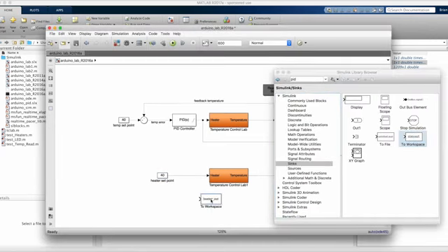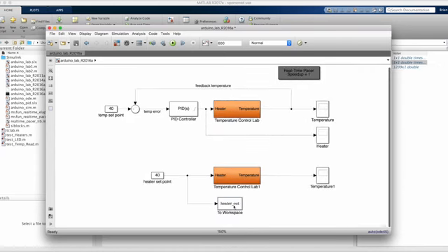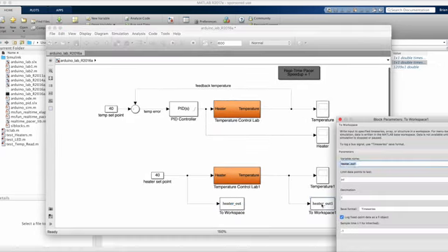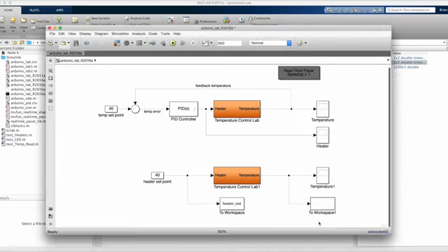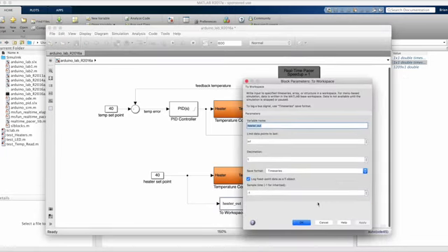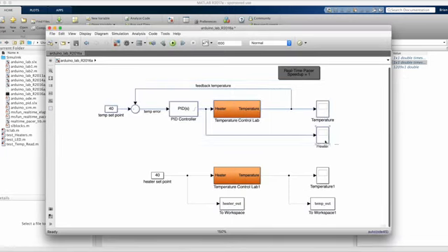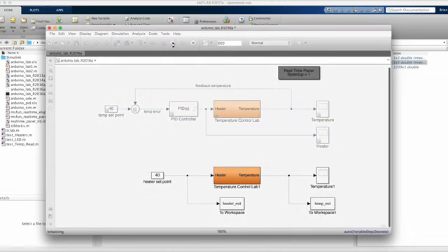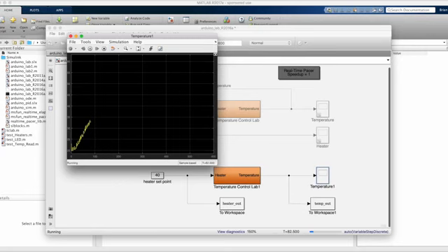For system identification, we could take the white box approach, taking note of the material properties and the dimensions and write out the differential equations directly. However, we have the hardware, so let's fit a transfer function to our real system. The way I'm going to do that is by applying a step function to our system and recording the step response. This is exactly what we did at the beginning of all of this, except this time I'm going to save the data in an array to use later.